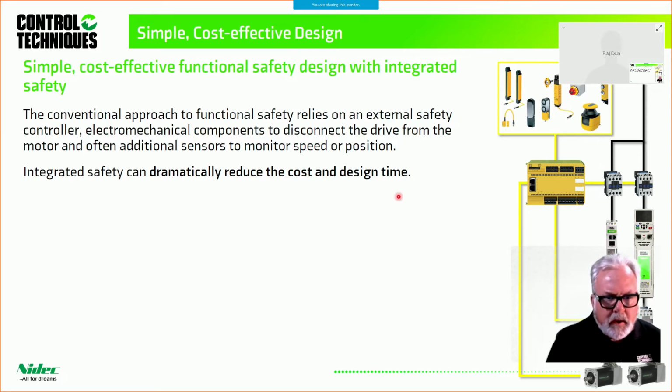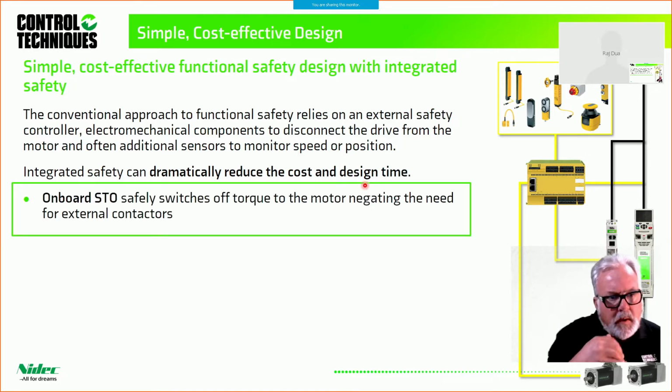So integrated safety reduces the cost and design time, specifically by the fact that our drives, the Unidrive M700, the Digitax HD, the Commander C300, have onboard safe torque off rated contacts. The use of those safely switches off torque to the motor. So because of the fact that we have the onboard STOs, there is no need for a contactor on the mains side, nor down here at the motor side, just by the use of our onboard STO circuits.